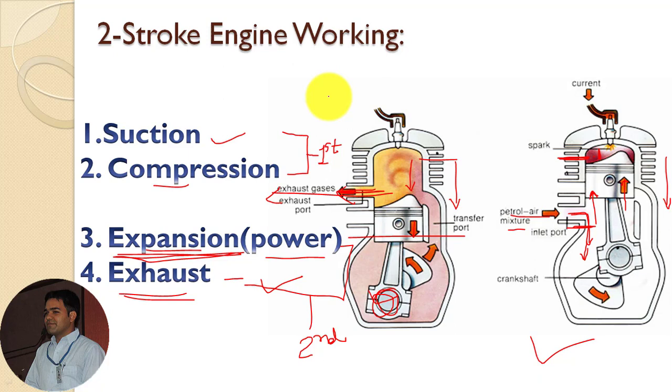I am again repeating, during the first stroke, during the upward movement of the piston, first it uncovers the intake port, so the suction process starts, and simultaneously it compresses the charge which is present due to the previous cycle inside the combustion chamber. So suction and compression simultaneously occur during the first stroke. At the end of compression, the spark plug ignites the charge, and the expansion process or the power stroke starts.